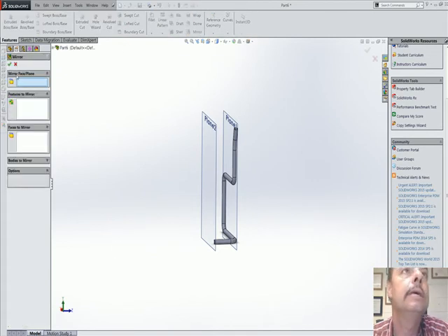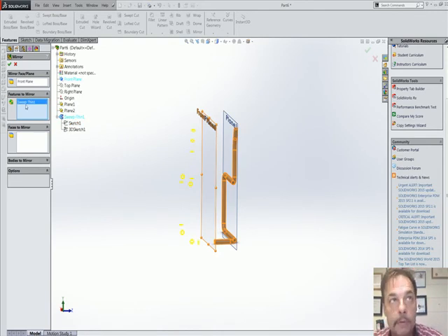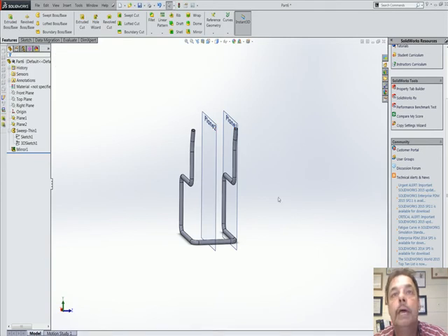Notice that it asks for the face. Now you can either choose it from here, which is the front plane, and features. We can choose it from here, or I can pick my front plane if you want. And actually, I'm going to pick my 3D sketch. Oh, features to mirror. Sorry, you gotta pick your sweep to mirror. Once that's done, you notice you got a little bit of a preview. Hit your check button. Okay.